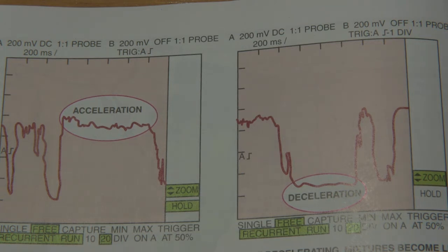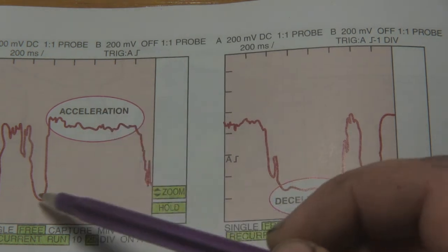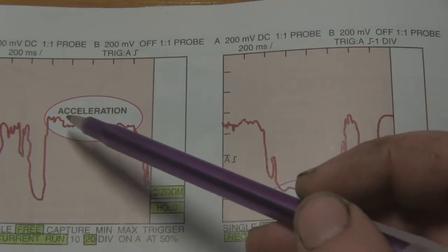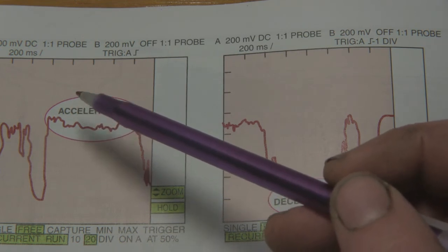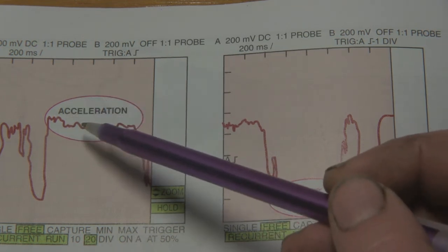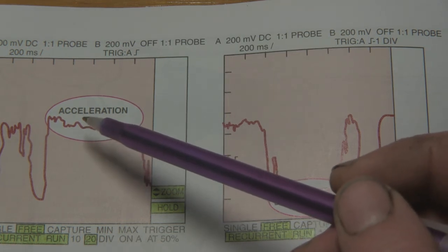So here's another issue. You can have oxygen sensors working fine in an engine that doesn't run well under wide open throttle due to other issues. So you might actually see this snap up because that's rich, but how rich? Is it 12 to 1 or is it 13 to 1? Is it 13.9 to 1? Does that vehicle start misfiring? Does it start having sputtering because it's got a bad fuel pump or a clogged air filter, or all those different things?